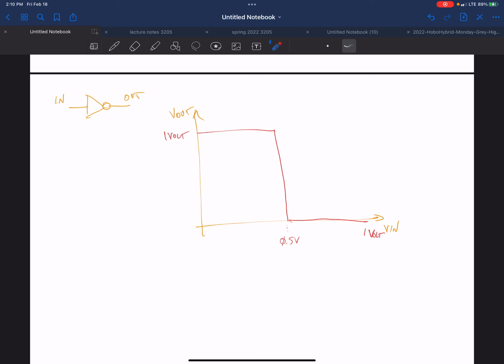They didn't have a situation where you could turn part of the circuit completely off, and your loads would end up being resistive and not fully capacitive. Okay? So again, in a CMOS logic family, because we have a PMOS network on top and an NMOS network on bottom, they're never on at the same time. Okay, it's guaranteed, once you settle, they're never on at the same time.